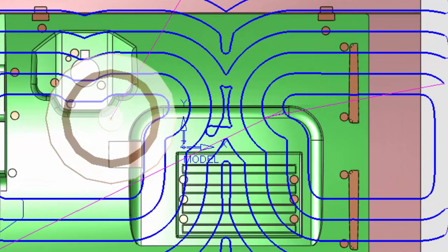I've stepped back and selected a 1/2-inch cutter and recalculated the procedure. At a glance, you'll notice stretch motions in a few areas. These are created with an option called Clean Between Passes. It allows the system to use a more aggressive step over while ensuring no nubs are left behind. You'll also notice all of the motions are rounded to prolong tool life.